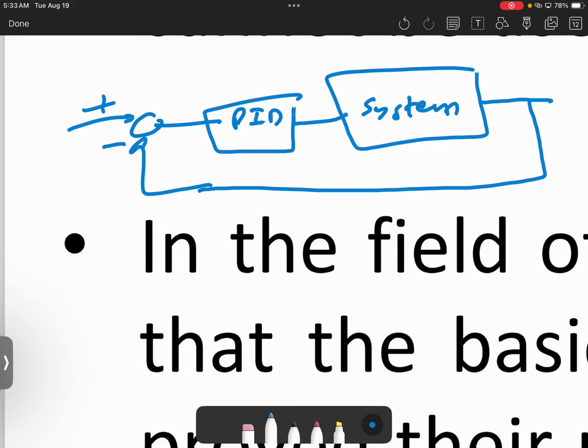But the good thing about it, we realized if you put the input as a step input, most likely it can do the job. If you assume the input as a step and add the PID, or if you need the input to be like a step, like increasing the car speed, increasing the temperature of the air condition, these kinds of small applications, it can do the job. Okay?